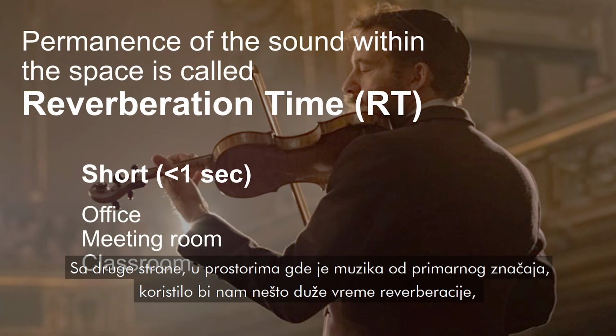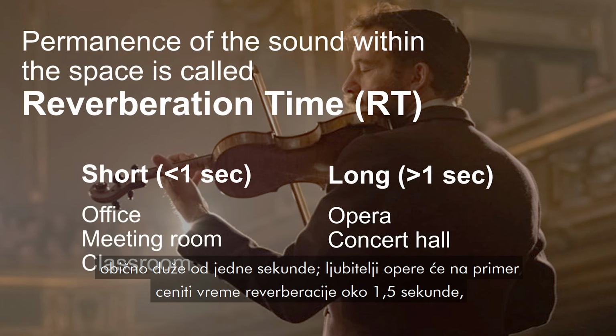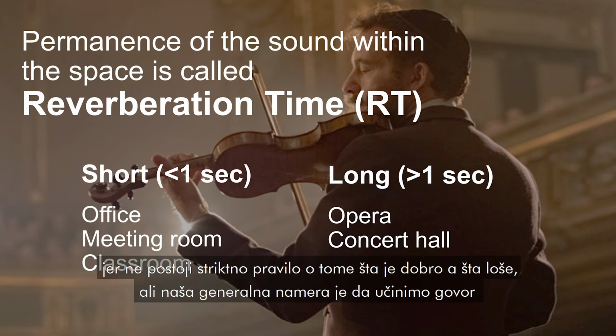On the other hand, in spaces where music is of importance, we benefit from a longer reverberation time, usually exceeding 1 second. Opera lovers, for example, will appreciate a reverberation time of 1.5 seconds, and it is said that Mozart might sound the best with a reverberation time of 2 seconds or more. So you can see there is a very fine and fragile limit between these values, and actually that's the beauty of acoustics, because there is no strict rule what is good and what is bad.